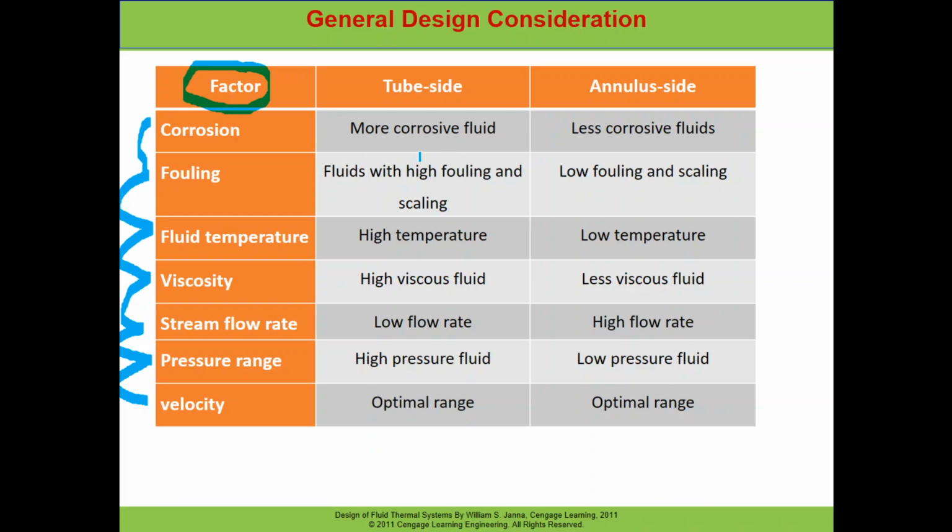And if it is outside in the annulus part, it will corrode the tube as well as the annulus part, the outer pipe also. So it is better to put the corrosive fluid inside the tube. The same thing applies to fouling also.